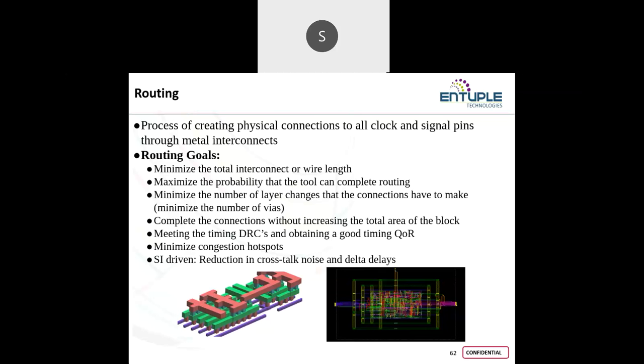Usually when I am talking about clock skew, again I'll take care of it with the balancing. Balancing means I'll be adding some clock buffers into the design, which helps me to meet my clock skew along with the clock latency requirements. So one way is building and balancing, and you also have the option to edit or modify your constraints based on the requirements to maintain your clock skew or clock latency. So any further queries? No, madam, thank you.